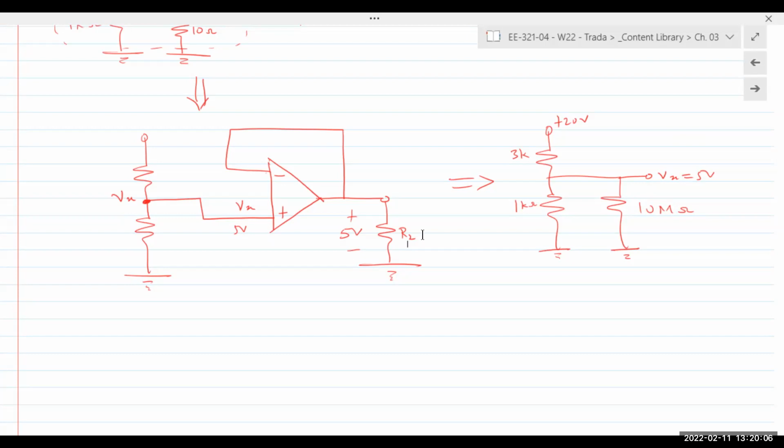It'll be somewhere less than 1 kilo ohm, probably around, let's say 9,990, perhaps. I haven't done this calculation, but you calculate this, and it might come out to like 4.98, 4.99. For all intents and purposes, as close to 5 volts as possible. But here I was just saying, even if you take the worst quality op amp, which has an input impedance or resistance of 10 mega ohms, you'd still get close to 5 volts.